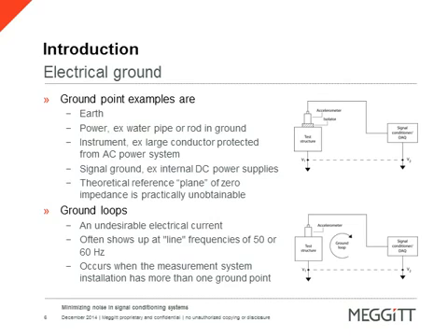The diagrams to the right, the top one, is the proper grounding technique. You notice that the grounded accelerometer has an isolator underneath it as it's mounted to the test structure, so it does not provide a ground path back to the signal conditioner. The diagram below is the incorrect form. The accelerometer is also grounded to the test structure, causing a ground loop for this entire system, which is not desirable.